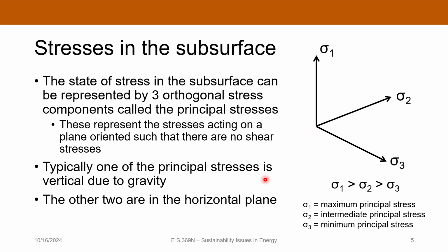Okay, so we have to think carefully when you're drilling a deep well about the state of stress in the subsurface. So we're going to talk a little bit of geomechanics and wellbore stability here. In general, in the subsurface, you can represent the state of stress with three orthogonal components. We call these the principal stresses.